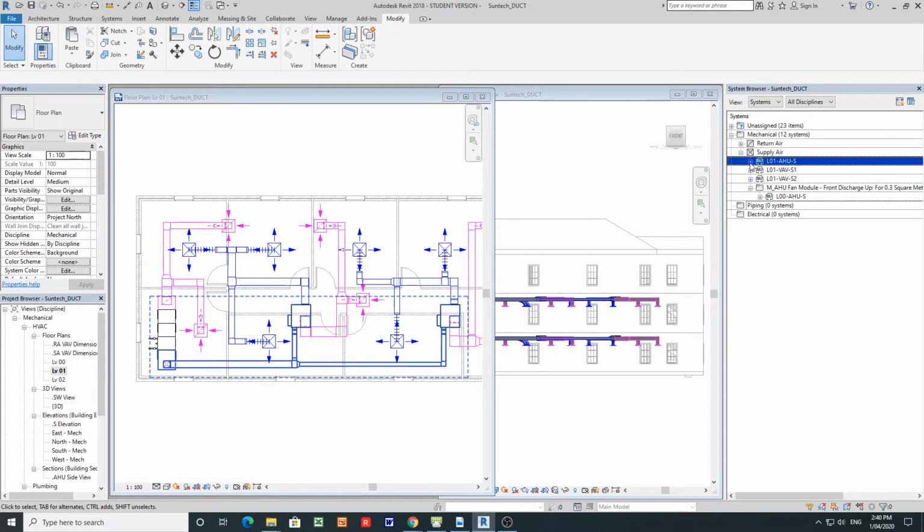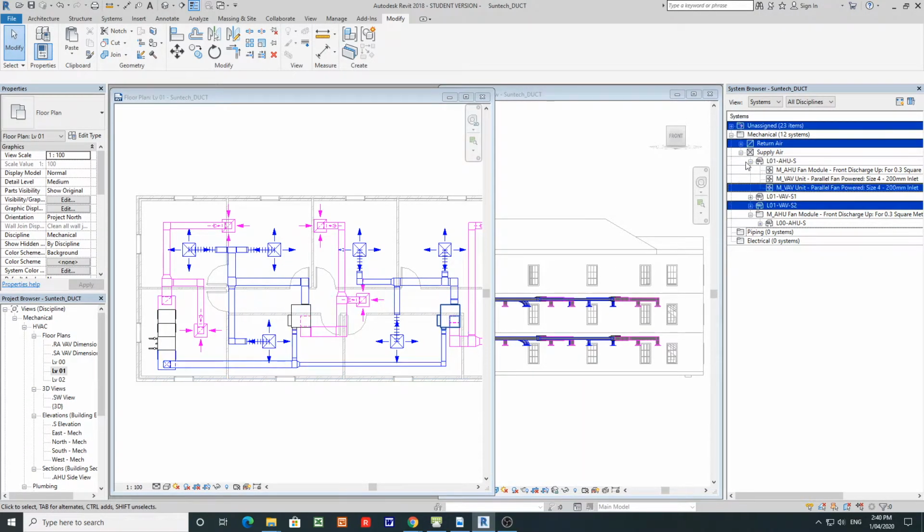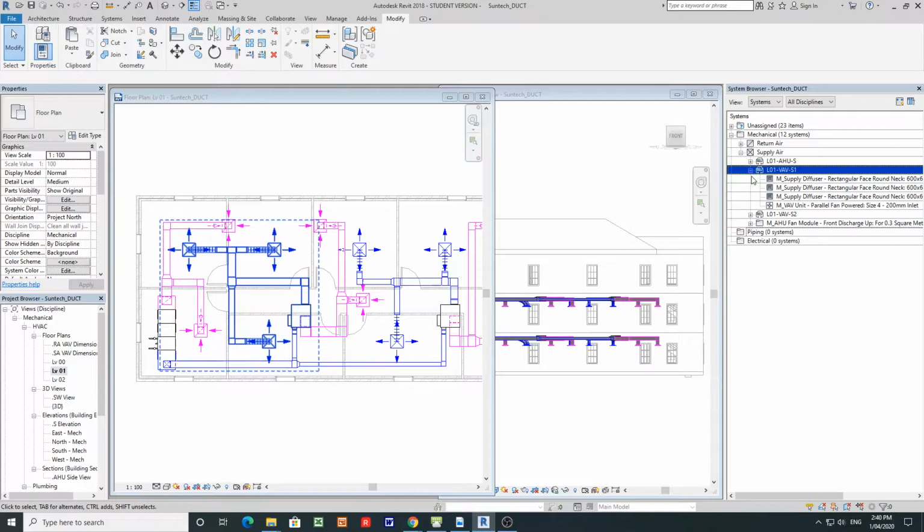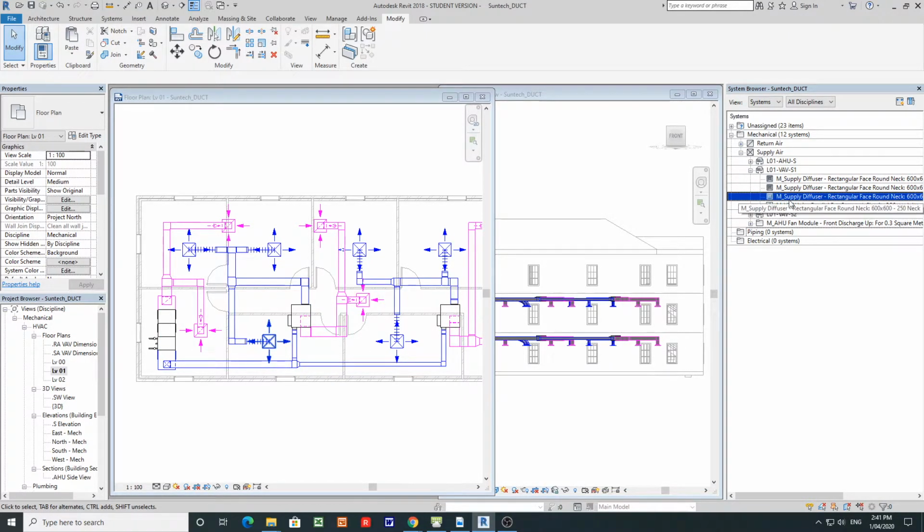The first one, the top of the level, is the AHU system, which contains two components, the VAV boxes. For the VAV box, you have supply 1, supply 2. Of course, if you look down, you have what we call the supply diffuser, and also a VAV box. So the next step is to go to the bottom of the hierarchy, which is the VAV system.